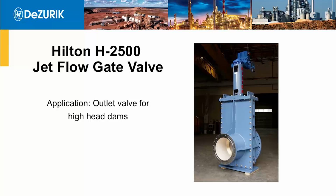Anyway, this is the second valve that we provide, and that's the Hilton jet flow gate valve, series H2500. It's good for outlet valves at high head dams. You will see customers say, hey, we want it even though the head is lower, but that's because they've got these valves probably installed at other facilities and they like them. But to install them on a low head dam is really overkill in my estimation.